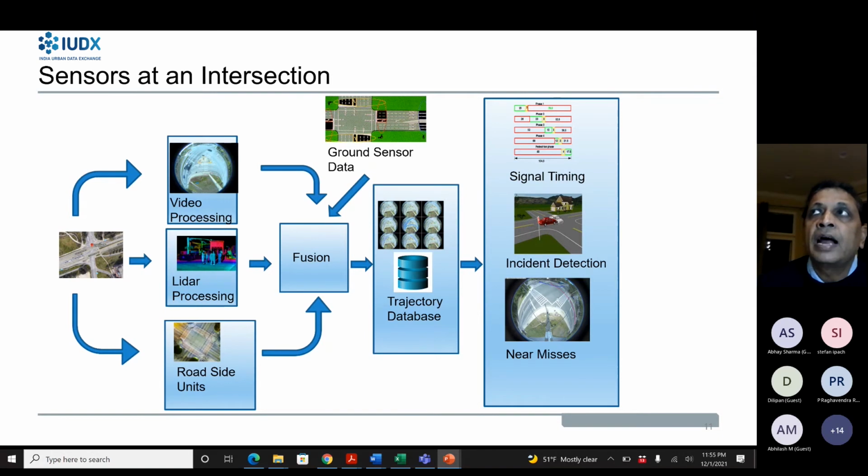Yeah. So right now what happens is that we get data from every detector, right? So generally, for example, if there are 3 lanes on the major and 2 lanes on the minor side, you will get 6 plus 4, 10 lanes, and there will be probably of the order of 20 to 40 detectors, and each of them will get data by the detector number, right? And we have the same problem to some extent, although the detector to phase and the detector to channel mapping, as we call it, or the arm mapping as you're talking about, is available, but sometimes it's 10, 20 years old, and there's reconstruction going on all the time. So some of that data information is missing, if you may, right? So we have techniques to be able to figure out which arm a particular detector belongs to, and I'll talk about it a little bit if we have time.